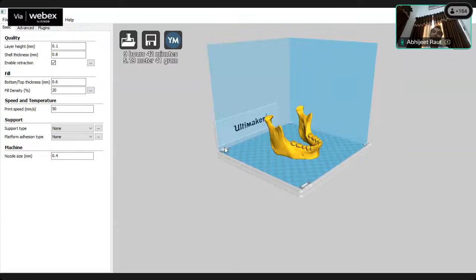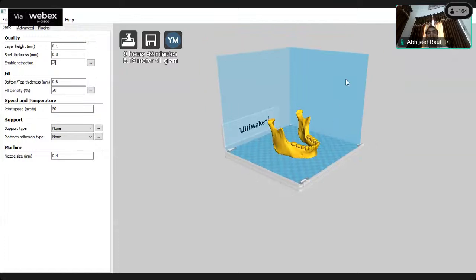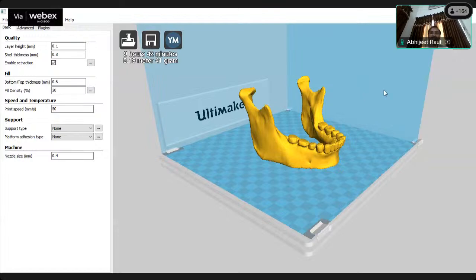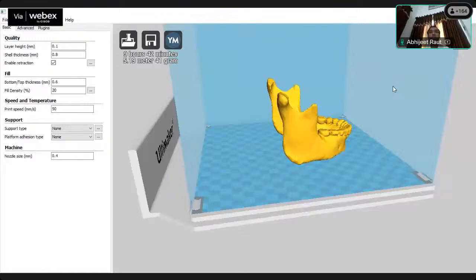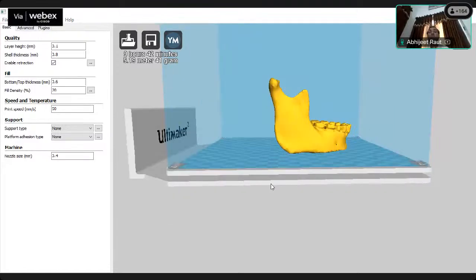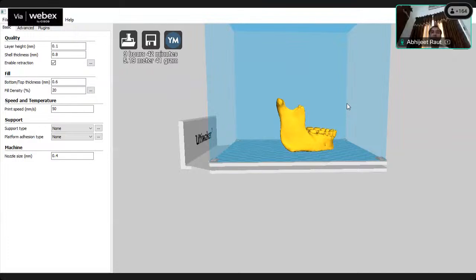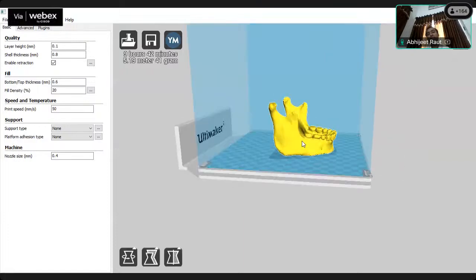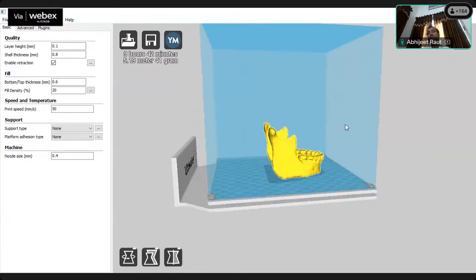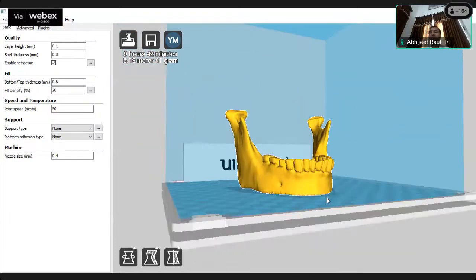Here also, remember the parameters. I think in some session you must have learned about orientation. You are aware of the Cura software. This is open source software you can use. Various proprietary software also exists, as every 3D printer comes with its own slicing software. So orientation in pre-processing, the orientation of your STL file, is very important.